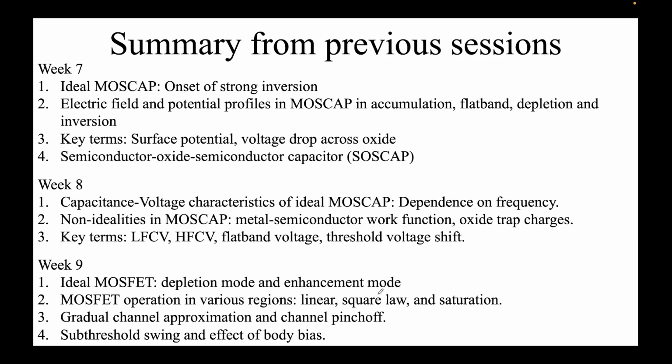Okay, so we saw what we mean by strong inversion. I'll iterate it very clearly, because we'll revisit this. Inversion means, although your bulk substrate is, let's say, p type, due to application of, this is your metal, let's say Vg you are applying. If you apply a positive bias, you will repel away the excess holes that are there, so you get something called the depletion. If you apply it further, then the electrons will accumulate at this interface. So although the bulk is p type, this interface is n type. This means it's an inversion.